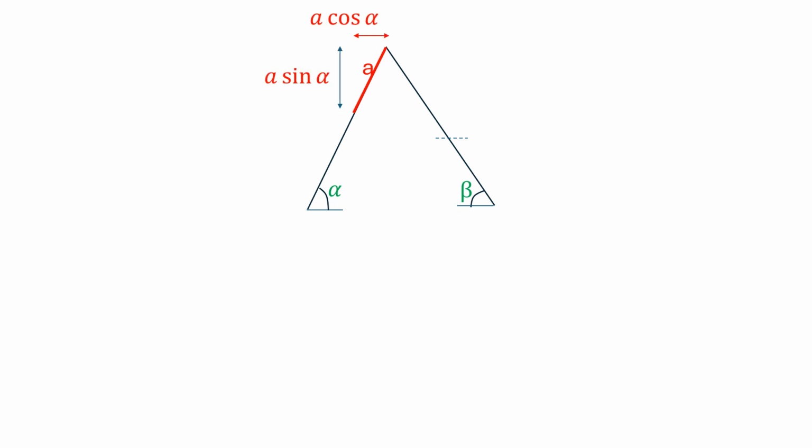After getting these elongations, we need to find out the resultant displacement. Since the bars are like this, the bar AB is subjected to axial compression. Let us say A is the compression or the shortening of the bar AB, and it will have its components in the horizontal and vertical directions, that is in X and Y directions, A cos alpha and A sin alpha.